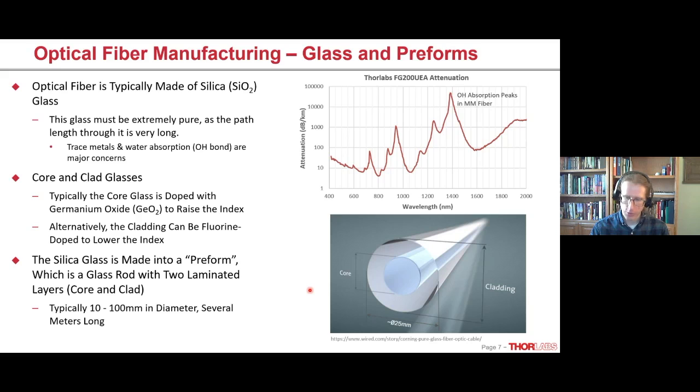But you can actually have many light sources of slightly different wavelengths, and each one of those can turn on and off at different times. The fiber, of course, can transmit a wide wavelength range. As an example, telecom communications are typically centered at 1550 nanometers, and we can use a device called a WDM, or wavelength division multiplexer.